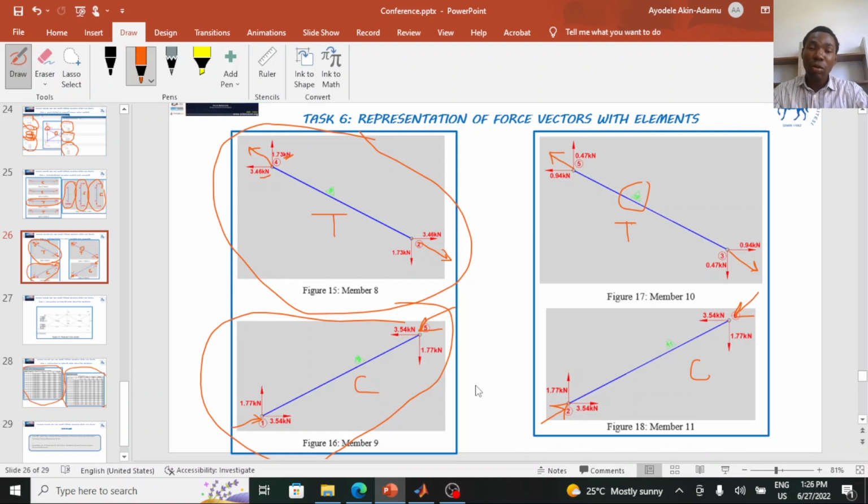So this is how we solve a truss problem using the finite element procedure by penalty approach. And in this penalty approach, I actually use the large stiffness, which I define as infinity. In my next video, I'll use the normal approach for the penalty approach, where the large stiffness is defined by the largest element in the global stiffness matrix multiplied by 10,000. So we are going to use that approach to solve this same problem in my next video.